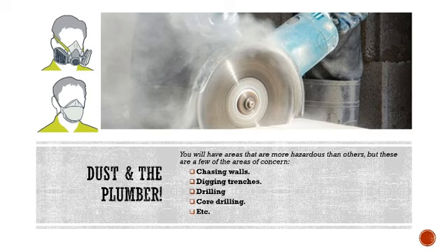What kind of dust suppression is needed then? For the chasing of walls, is that person chasing 8 hours of the day in order to make sure that the entire area is opened for the piping? Well, all of this needs to be taken into consideration. Now, why do we mention that? Well, the risk assessment is the most important tool here in order to, first of all, prevent this hazard so that the dust is minimized to an acceptable degree. But at the same time, the safe working procedures on working with tools that create dust must also be considered.